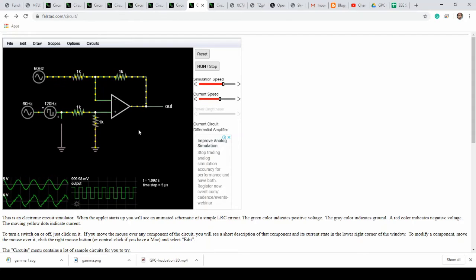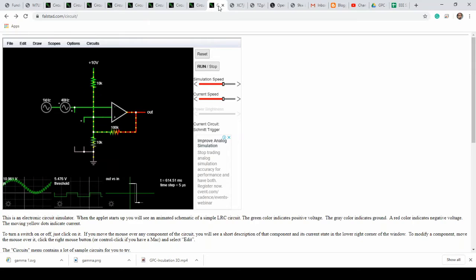It's a simple circuit, and you'd be able to realize it in this form factor. Now let's look at another application, the Schmitt trigger. When you want to trigger, for example, an SCR precisely based on the waveform, this circuit is what can help you do it. Now you look at your input, it's an oscillating sine wave, and it's got two components in it. One is a 1 kilohertz and a 40 hertz combined together, and that input is fed to your op amp.